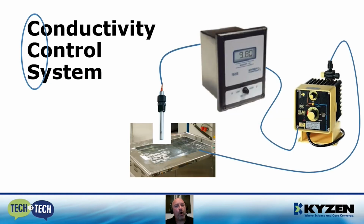So now that we have all three parts put together, we have what we call a conductivity control system. We have a probe, we have a tank full of conductive materials, we have a controller. The controller is talking to the pump, and the pump is adding chemistry into the system to get you the correct